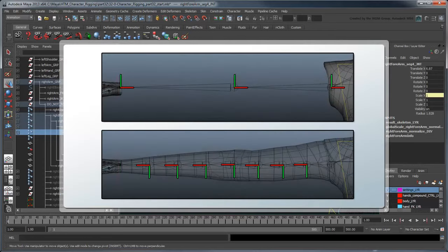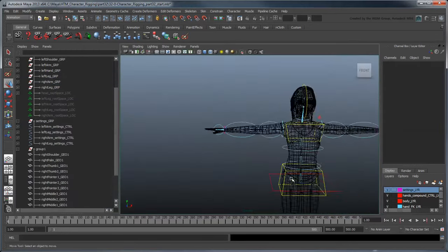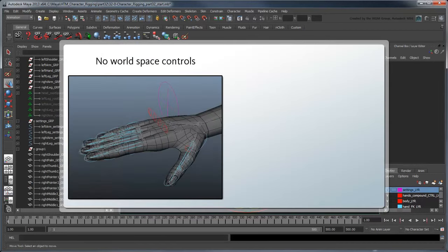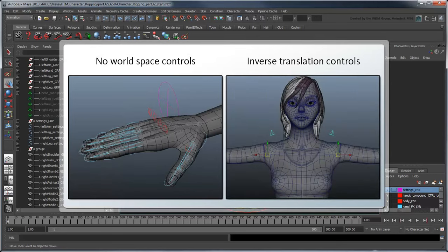This is to ensure the twist works correctly, and is okay because we will never interact with these joints directly. Finally, the hand and shoulder present an interesting case. Because of the nature of the hand manipulation, and because the shoulder's translation-based controls actually do require an inverse relationship to its left counterpart, we can use a mirror-duplicated version of both these body parts.